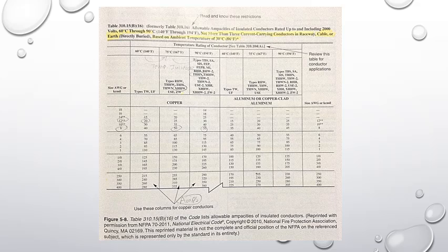All conductors will be THHN copper. Because this situation meets the 3 criteria listed above, the conductor size can be picked from Table 310.15(B)(16). It appears that 14 AWG is ample, but there's an asterisk next to the 14 in the table.